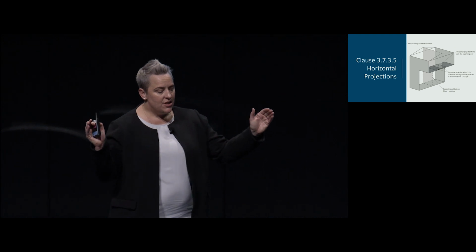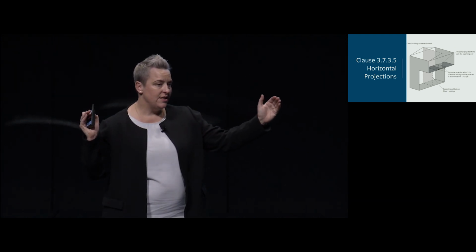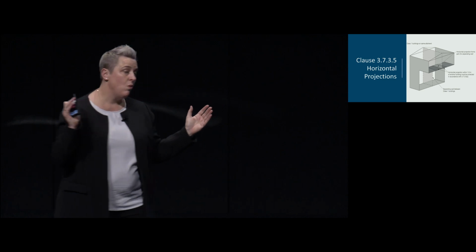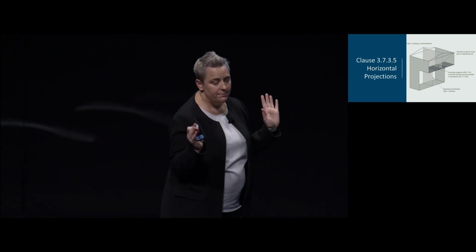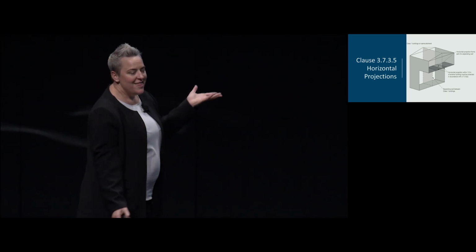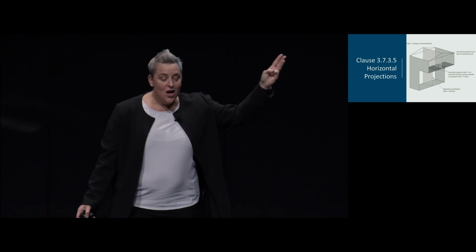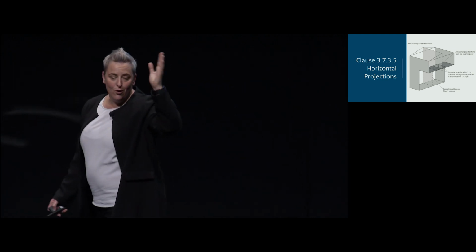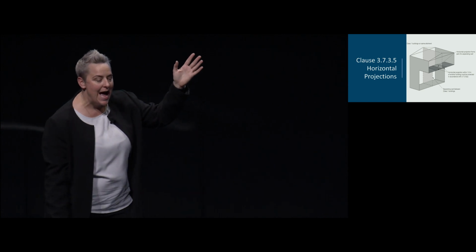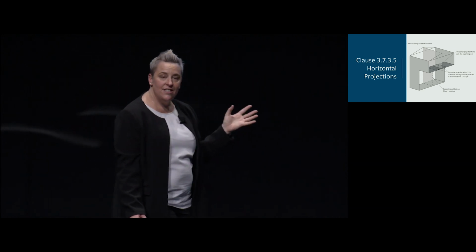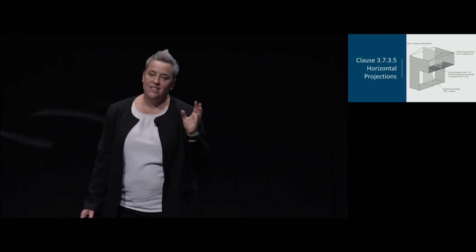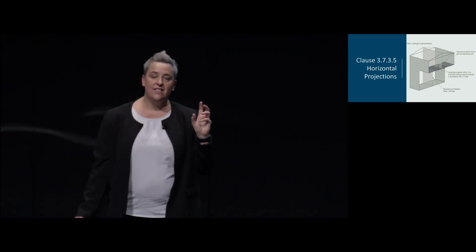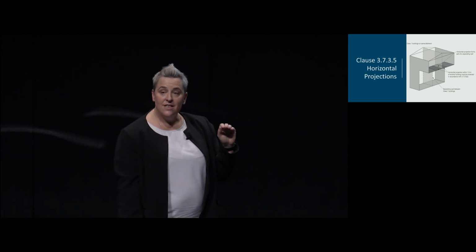So what you need is that you need that protected. So on either side of the wall separating the class 1s, you need 1.8 metres of protection. So the protection, you've got three elements. Three elements. So a floor or ceiling, or a floor or soffit system incorporating ceiling or soffit with a resistance of the incipient spread of fire. Or you can have your fire resistance level, so your FRL of not less than 30, 30, 30 from the underside.